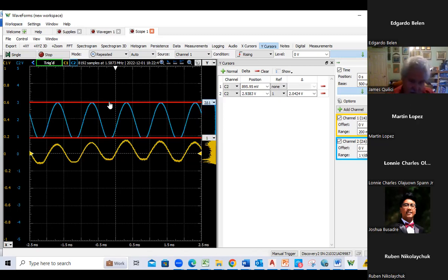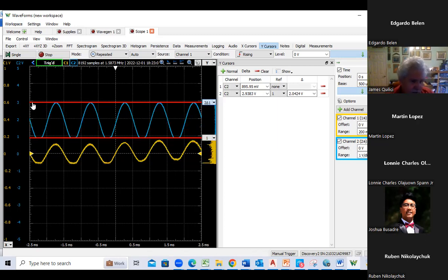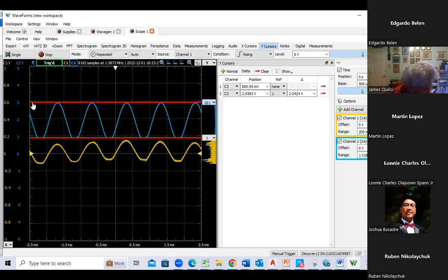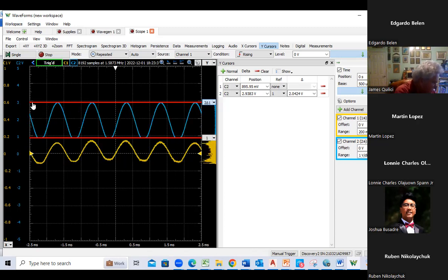Yeah, I've got 2 volts divided by 0.2. So I do have my 2 volts peak to peak gain. Not ideal. Again, it would be better. I'd have to go back, I think, and recalculate. I think ideally I want the collector voltage sitting closer to 3. Maybe I can do that real quick. Hold on. Let's see. 1.26. I wanted 2 volts divided by 1.26 equals. Okay, I'm going to try to drop in a 1.5K. Yeah, 1.5K, and see if that does it for me.